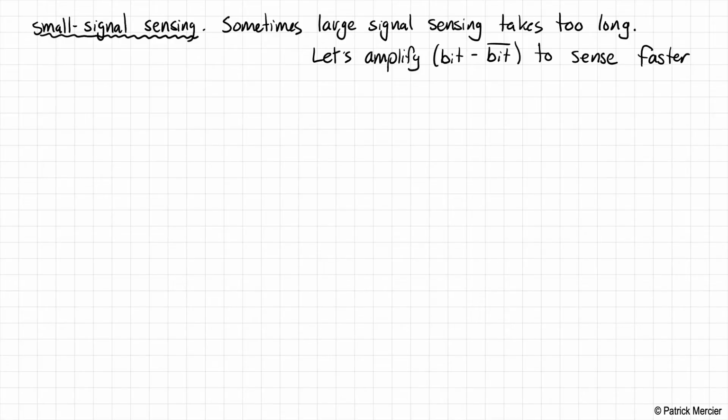So that's definitely possible. We could just use a normal differential amplifier, like one that you've studied for use in 102 or 164 or something like this. That'll work perfectly fine. However, we are digital designers here, and so perhaps there's a better thing we could do that consumes less power, right? A differential amplifier requires a static bias current that will consume static power. We don't like static power in our digital circuits, so let's think about something different that we could do.